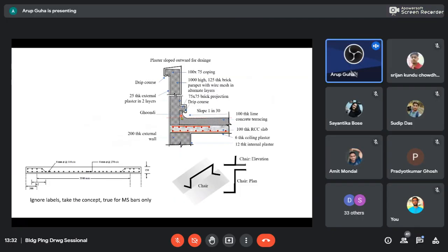The thing is that this is a separate medium, so alpha for thermal expansion will be different, so there will be weakness here due to thermal changes. The face here could be dissociated, so if water can come somewhere here, then it is an easy path to go through this and soak or affect your slab.